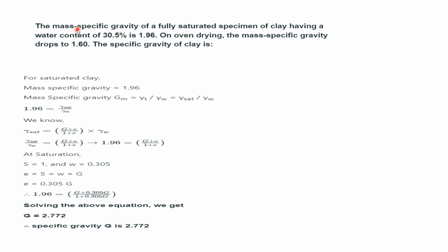When your soil is completely dry, all the voids will have only air, there is no water, so we call that dried soil. Whereas partially saturated means, in a full mass of soil, some voids are with water and some other voids are with air. So it is neither saturated nor in its dried state. Some voids will have water, some voids will have air, we call that partially saturated.